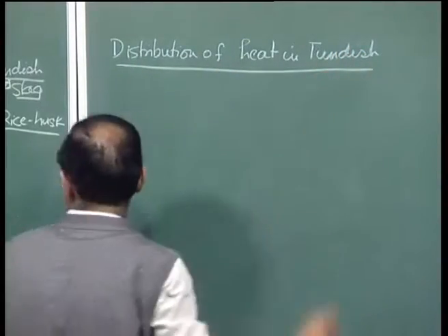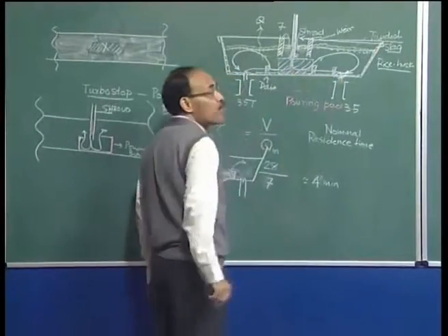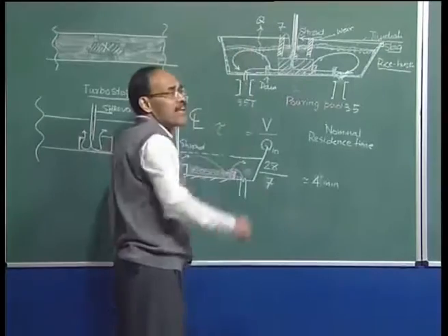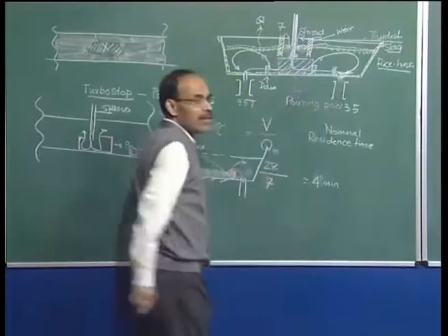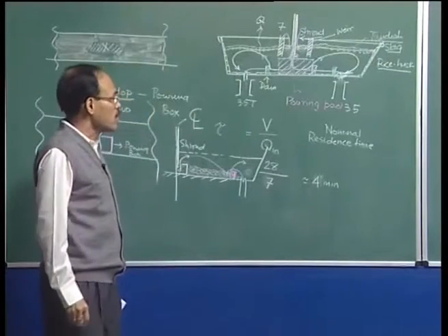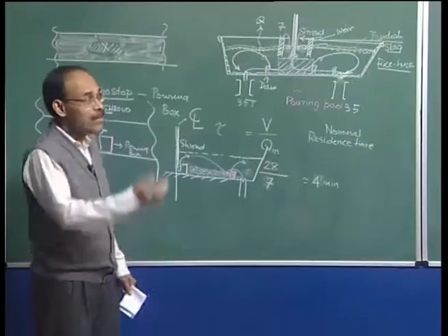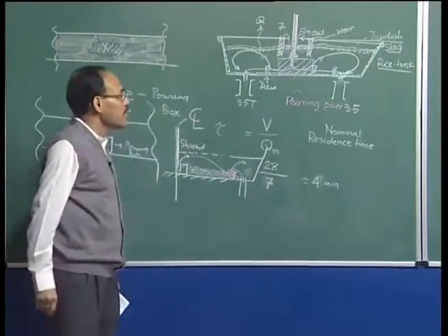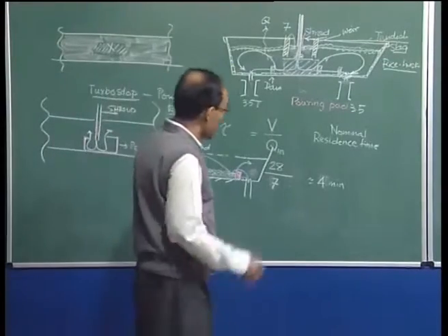It is often required that if the temperature drop of this material is significant, suppose you are operating with not a thick slag, with no tundish cover, in that case there can be a significant amount of heat loss, and in that case in the tundish it may be necessary that the material is heated up.